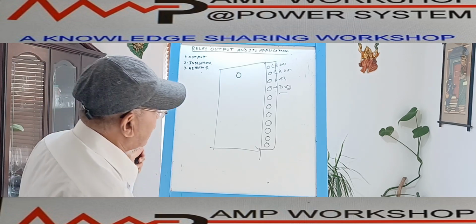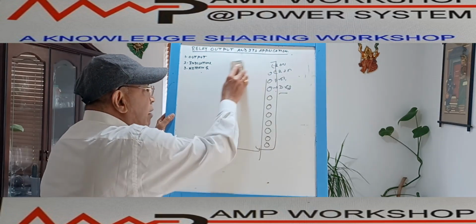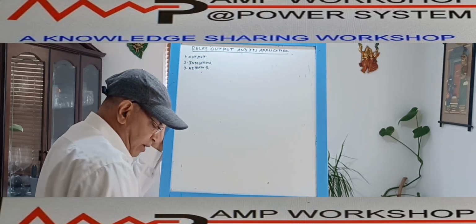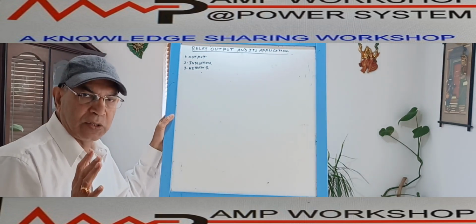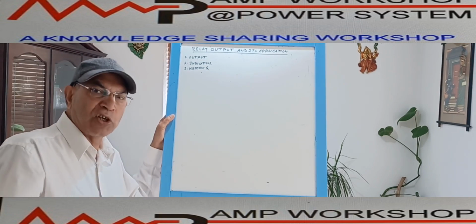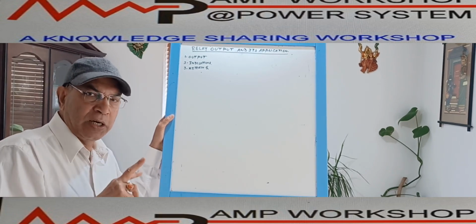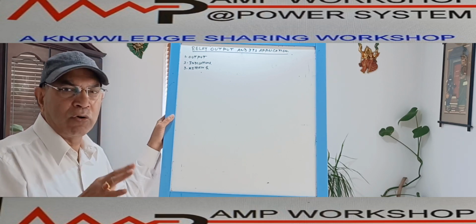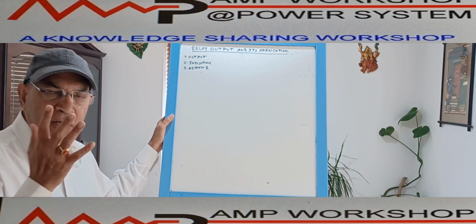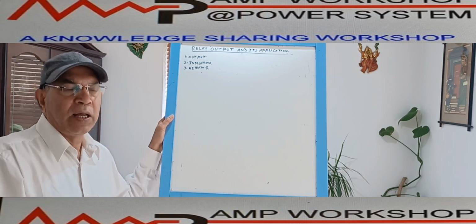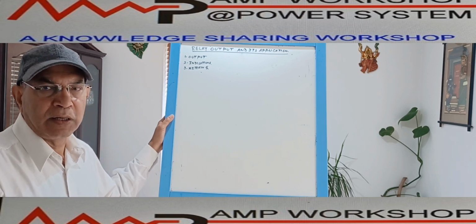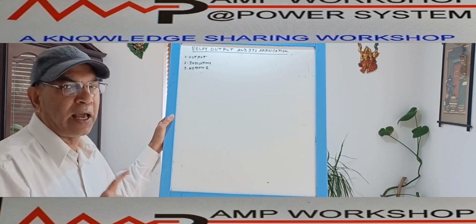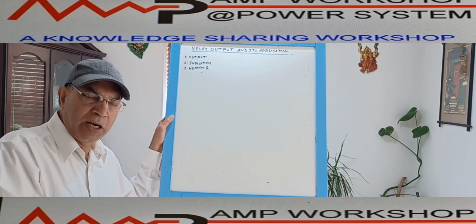In the electrical circuit, normally in the old days and even nowadays, we use a multifunction meter. The multifunction meter monitors all the parameters. This protection relay also does the same thing. That means the protection relay has a dual function, even a triple function. One is a control interlock function, one is your protection function, and it can do the metering function. But a multifunction meter only does the metering function.